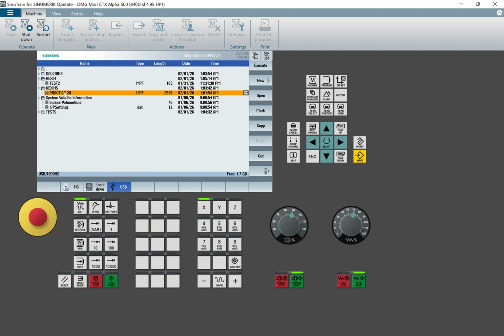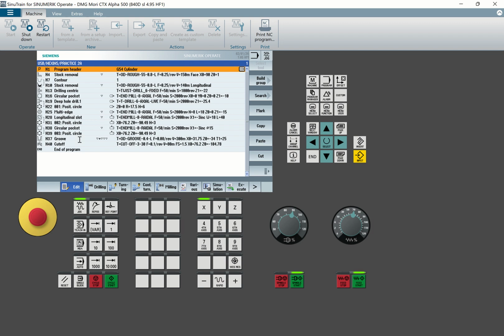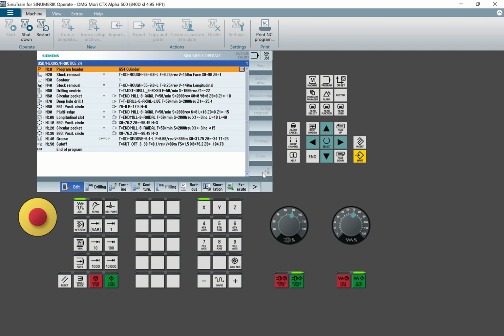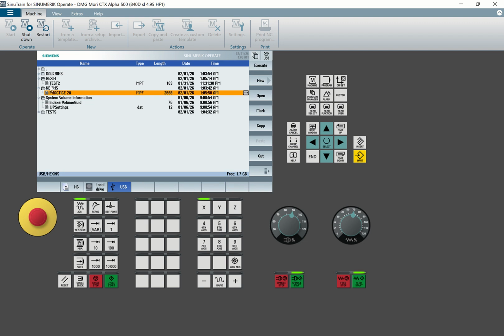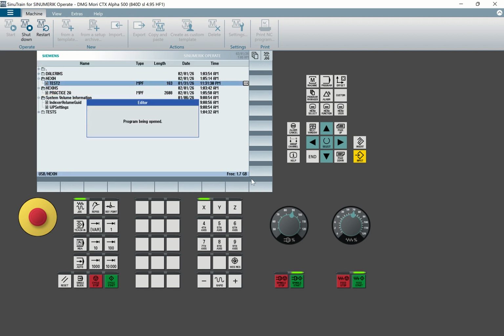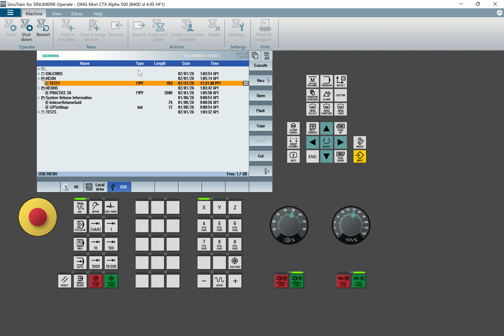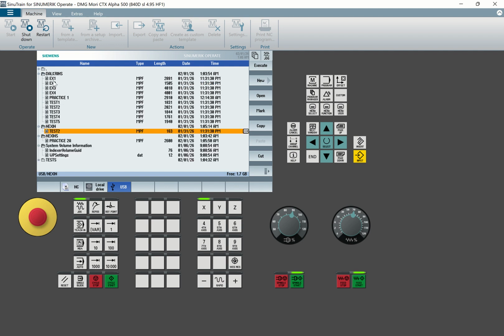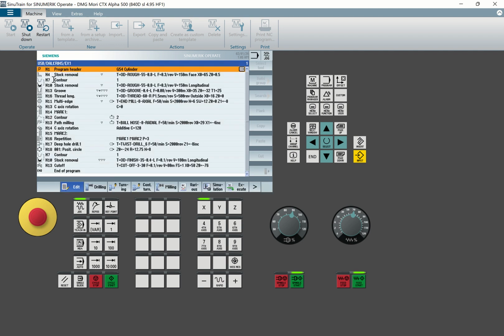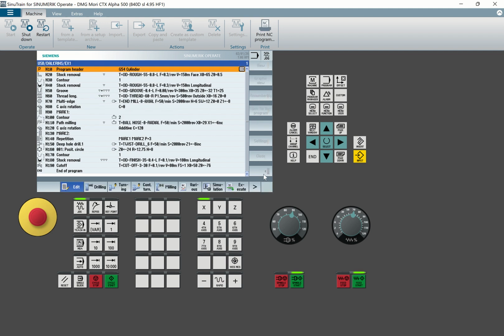And to access this program, for example, I can open the program here. This is a program you have created. And then I can even do numbering. I say now number from maybe 10 to 10, accept. It will automatically save. If I go to Program Manager, I'm able to see all these programs. For example, if I click on Test 2, open it, you see these programs. If I go to Program Manager, I can go to another different entity. For example, exercise this. I click Open. You're able to see the program. I can edit from the USB one by one. Then I can now take my program to the machine.